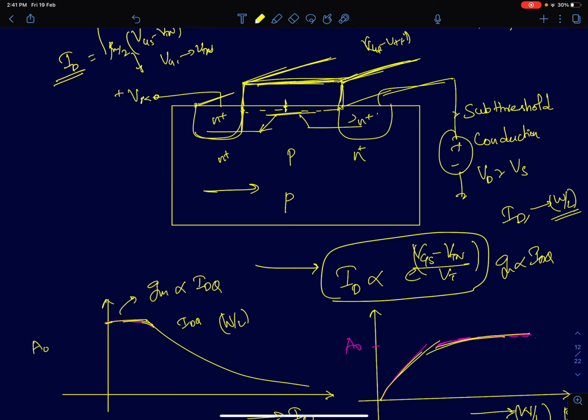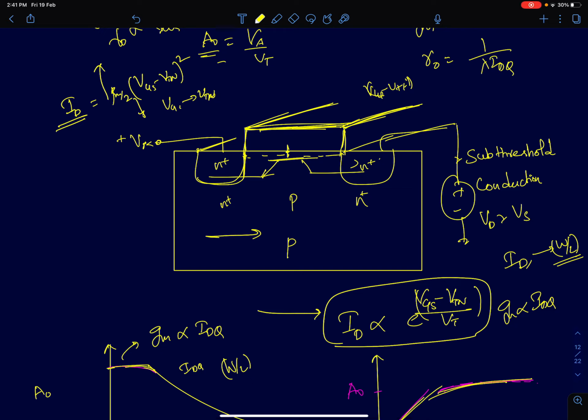How does that happen? One can intuitively see here, there is an NPN transistor, with N plus being the drain and the emitter being the source. A parasitic NPN transistor is automatically formed in a MOS structure. Normally, the surface region where there is conduction in strong inversion will be populated by electrons, so there is no such base region.